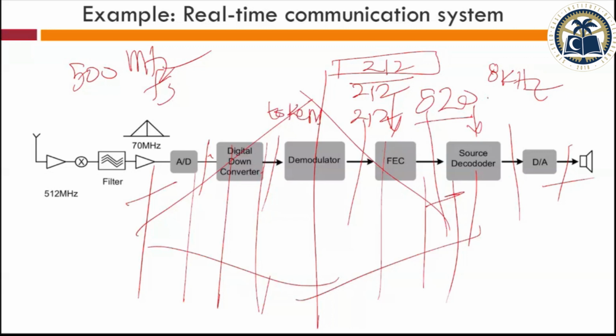So there is this concept of firing, that you have enough tokens. There is a concept of token, that you are collecting tokens, and whenever you have enough tokens, you fire the next block. Okay, you say, okay, next block, you start processing. The simplest design is that at the start you collect tokens, and tokens are nothing but the number of samples that are input from one block. So whenever you have enough tokens, you fire this node. You fire the node, and as the result of firing, you generate more tokens here, the output. Now you have these tokens, you fire this, and you have more tokens.